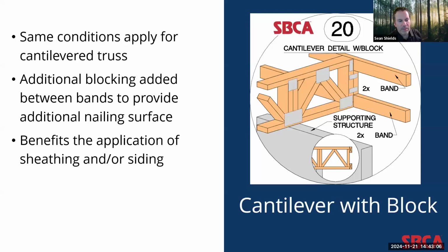Now, again, in some instances, this block wouldn't be required. It all comes down to sometimes local framing preferences. And sometimes it comes down to, again, those rotational or lateral forces may be a little bit stronger. So calling out a little bit more or providing a little bit more nailing surface area is appropriate.